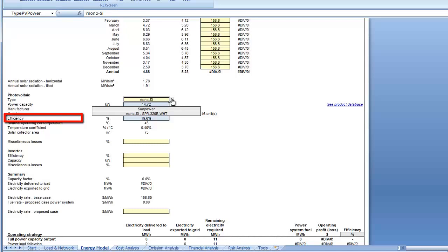Note that PV modules produced after 2012 are likely more efficient than what is indicated in the RETScreen database. For example, while 15% is a common efficiency for crystalline panels, many new modules provide efficiencies above 16%. For SunPower, the current manufactured data indicates a cell efficiency of 22.5% and a module efficiency of 20.1%.